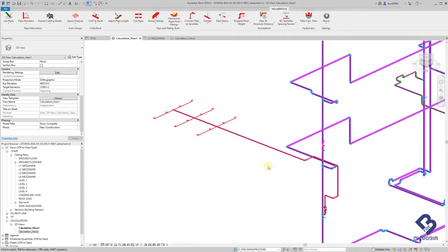At this point, there are a few options in order to complete your calculations. Within the Microbim Fire tool, there's the ability to export calcs to different software that you may be more familiar with. Hyena, FHC and SHC are all file types that we can export data from the model out to import into those. We also have SHC calcs within Revit.